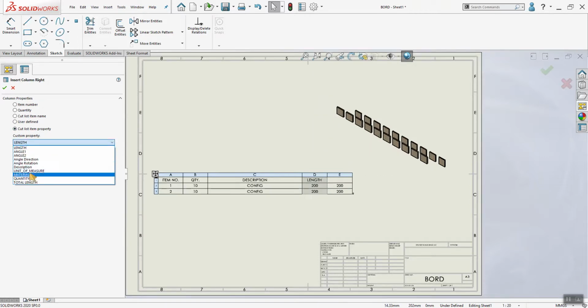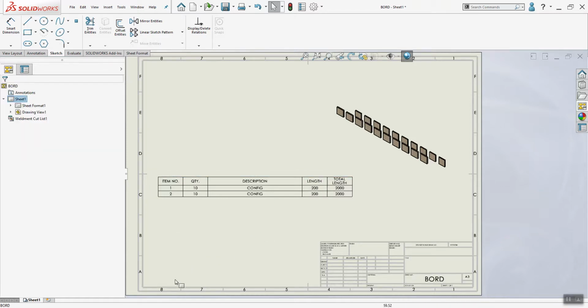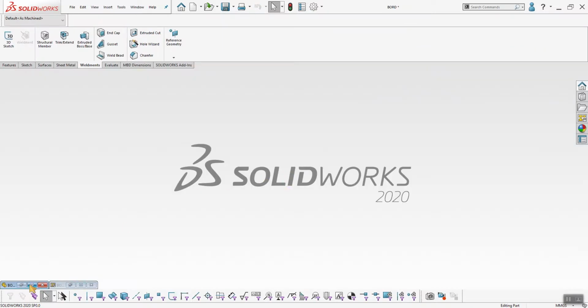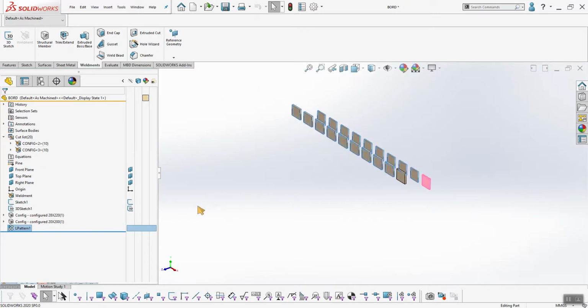you see there's no custom properties here anymore. We have material, pine, but that's from SolidWorks itself. It's not what we added, you know. We have total length, and whatever we want to put in, right? So how do we add it easily? We don't want to go in and type on all these 20 different bodies, right?